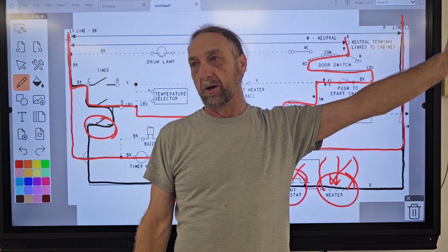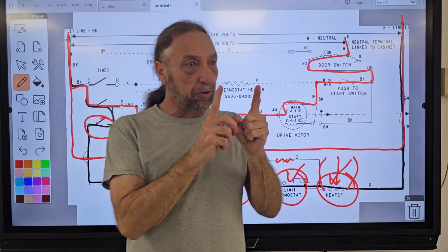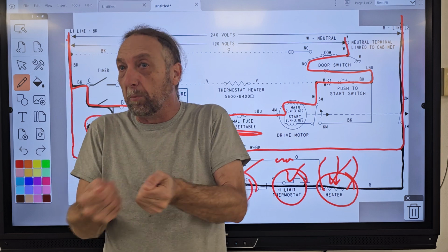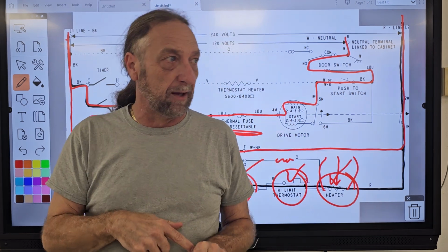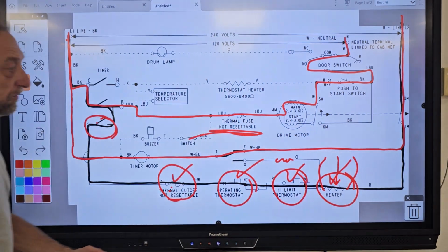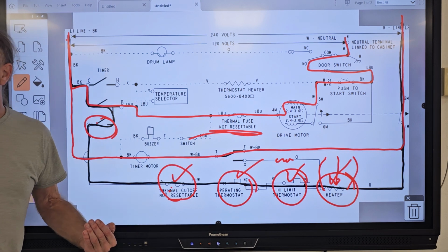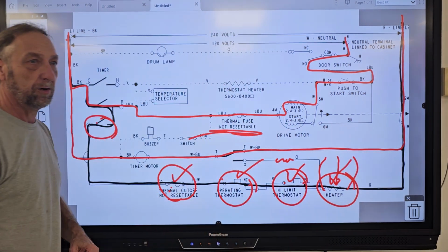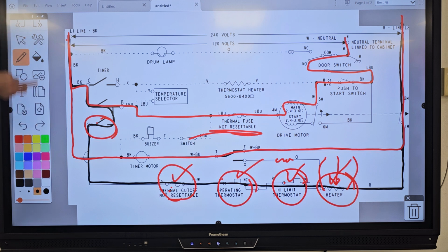We'll practice that when we come back after Christmas, okay? But the other thing you want to get are those little computer leads, those real skinny leads that can get on a plug on a board, because sometimes your leads are too fat and they can't get in anywhere to make a test, okay? So we're going to check voltage here. If I don't have voltage here, how do we troubleshoot this? Do we just go to each part and say, okay, I'm going to check this part, I'm going to check this part, I'm going to check that part? You go to neutral with one meter lead, and then you'd go back with your other meter lead, checking voltage.